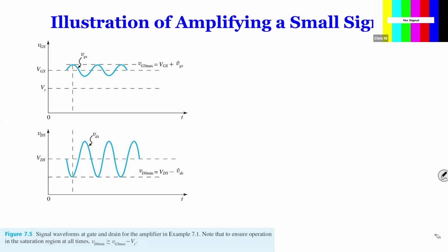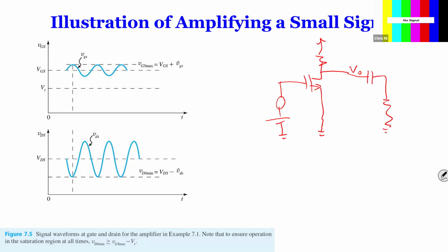So basically, let's say we draw the circuit like this. What you're doing is here, you add a capacitor, then you add your load resistance. And then here will be your VO. Your VO is going to be up there. Now for the input side, there are also different ways to get the input, but we'll touch that later on. For now, we just add the input together, DC and AC, to get the input side.